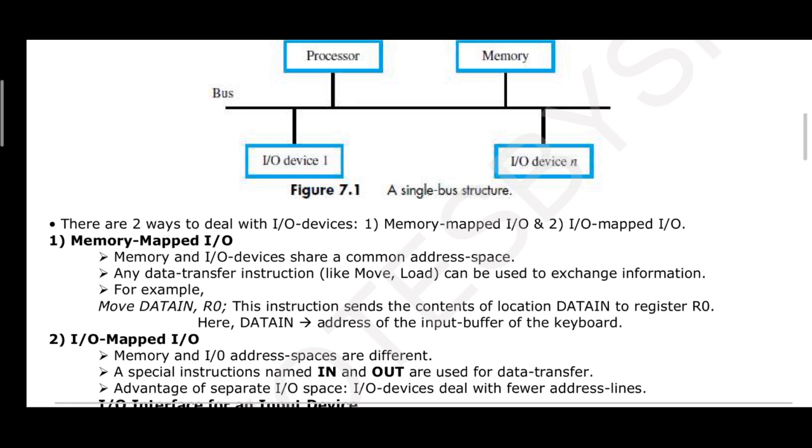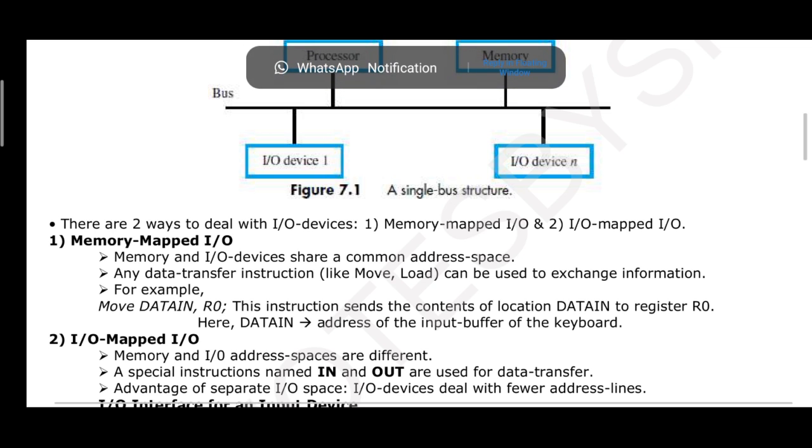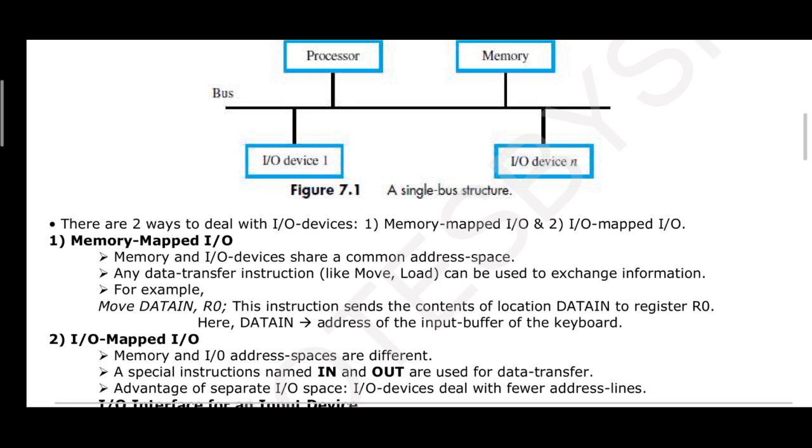So, recall the bus: there are three types of bus available, data bus, address bus and control bus. The data bus is used to transfer data from one peripheral to another peripheral. The address bus is also used to transfer data, but what type of data? Address information. It is a special type of bus that carries only the address information, or location identity, of the device. And the third one is the control bus, which transfers the control signals or control information only.